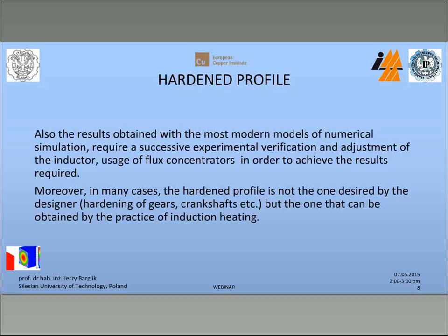And of course, it is also possible to discuss and decide about the hardened profile. Nowadays, there is no problem to elaborate models for numerical simulation, and such models supported by a well-planned experiment are good for prognosis of the hardening profile. Characteristic is also that nowadays we could use inductors for induction heating before the treatment. We could use flux concentrators.